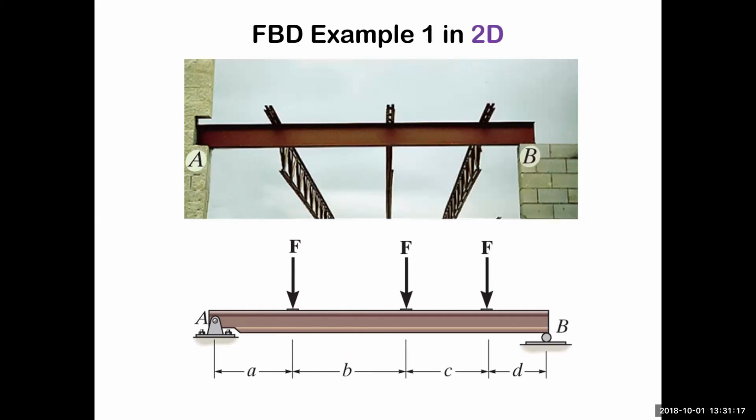So another example. Well, actually, now we're just going to do a few examples, right? In this problem, you have a beam resting across an opening in a building, and you could imagine this beam is probably anchored on one side. Maybe it looks like there's a little bolt there at A sticking up. I can't really see, but that anchor could be modeled as a pin. It's not really a pin in the sense of what the diagram below looks like. And then there'll be a roller. Again, that just means that the beam could expand and contract due to thermal fluctuations, because it's going to do that. And then the joists that are resting on it are replaced by simple forces.